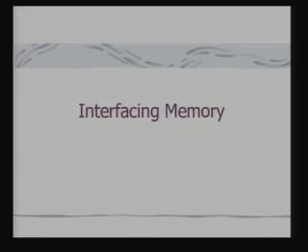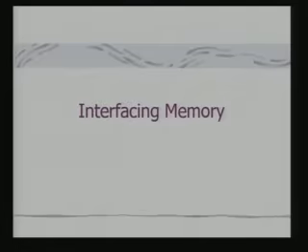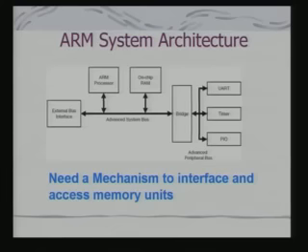Now, once we have these types of memory, we shall see an example of interfacing these memories with the microcontrollers that we have already studied. In particular, we shall look at ARM. If we go back to the ARM system architecture, obviously I have on-chip RAM, and we need to know how to use this on-chip RAM, but we can also have external RAM connected to the system.